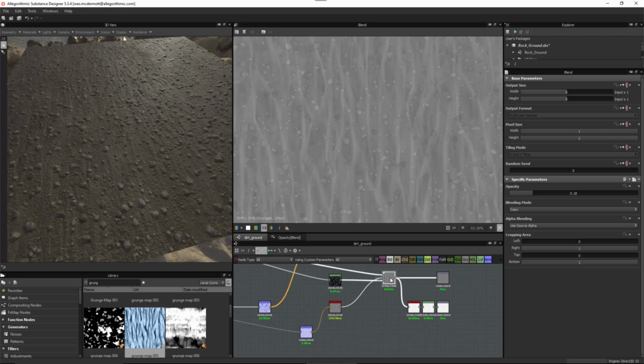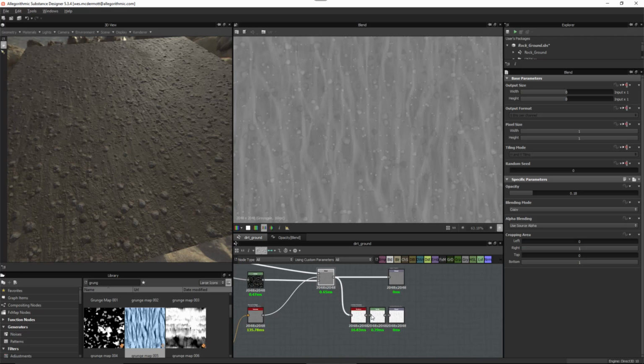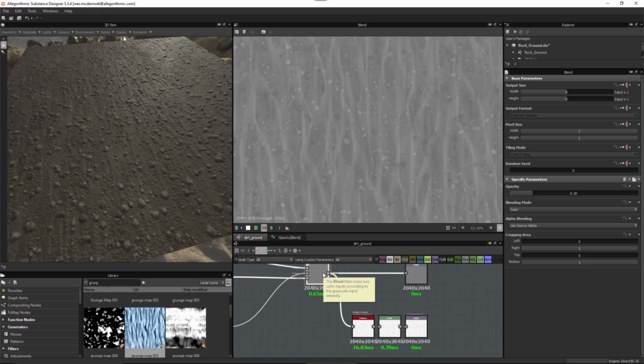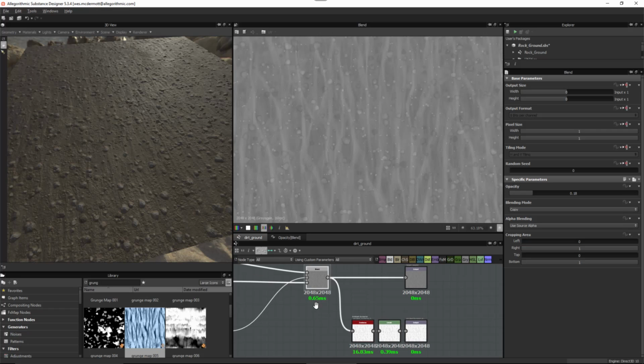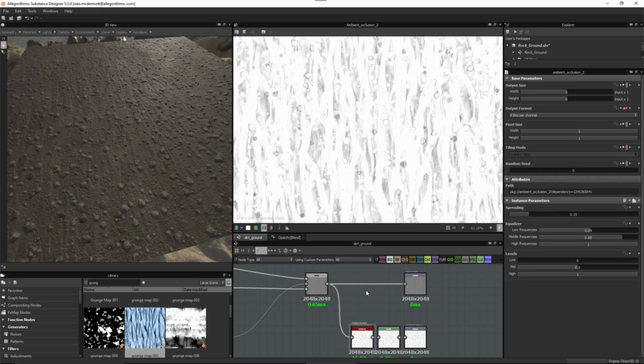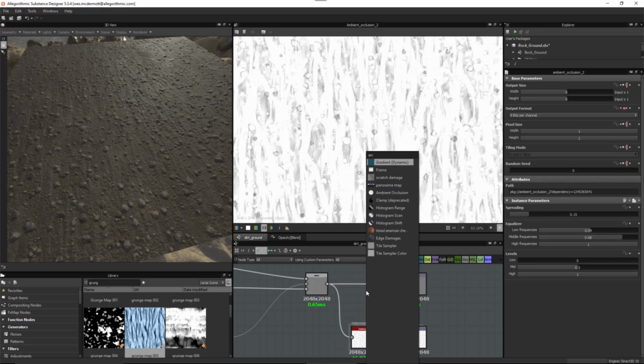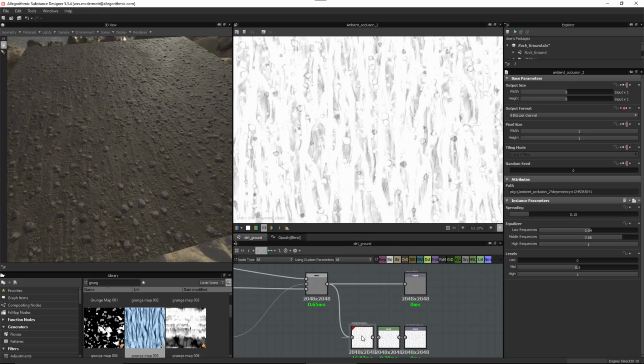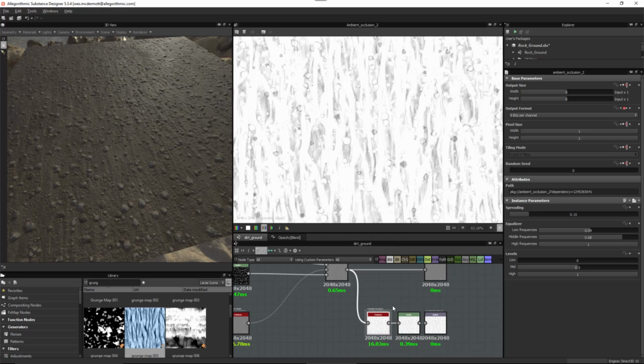While we're here talking about height, I just utilized this height information to create my actual ambient occlusion. From the height, we can grab our ambient occlusion node. If you hit the space bar and start to type in ambient occlusion, we have a node here that allows us to generate ambient occlusion. Here you can see that I just used this node. I've got options here for my spreading and so on. And I'm just using this node to generate some ambient occlusion information for my shader.